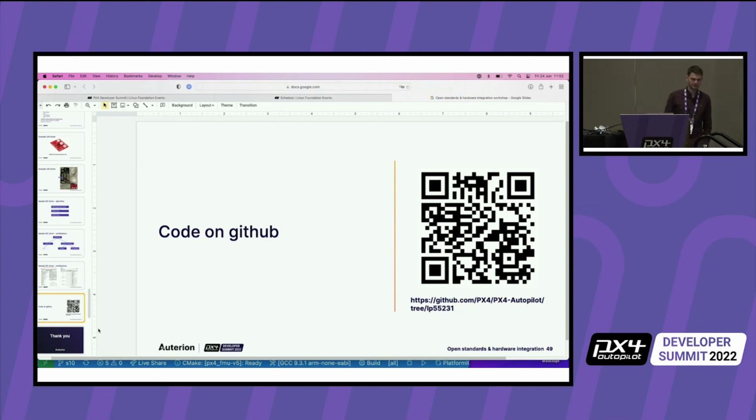Yeah, a very good reference for a serial, like a binary protocol driver? Yeah, so the GPS drivers are all serial drivers essentially. You can have a look in those. That'd be a good starting point. It's the only real serial device we have. There's the PX4 I/O, which is connected over a serial, but that one uses its own proprietary little driver that goes directly onto the STM32 and goes around NuttX. So don't look into that. That's something you want to get rid of.